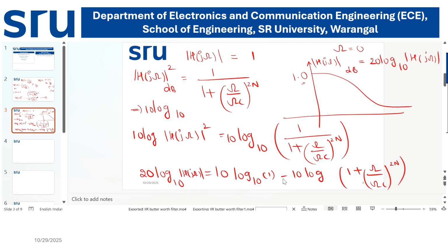Now if I observe the same characteristics, it has a passband frequency, stop band frequency, passband attenuation and stop band attenuation. The y-axis starts at 0 and the x-axis is omega. Sometimes omega is equal to omega p, the passband edge frequency, and sometimes omega is equal to omega s, the stop band edge frequency.